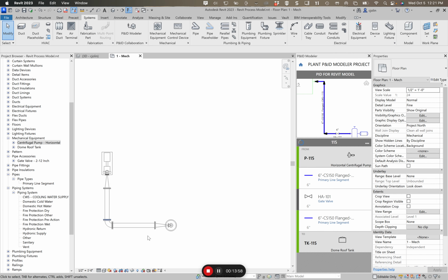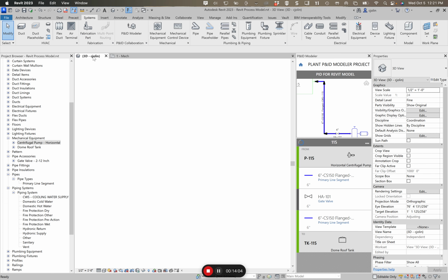With this modeling tool, it won't give you that connection until the first transition. And so our 3D model now shows us the piping as being 1.25 inches coming out of the top of both the pieces. And then once we get through that first transition, it changes to the 6-inch. The weird thing about this is this doesn't show up as being an issue.